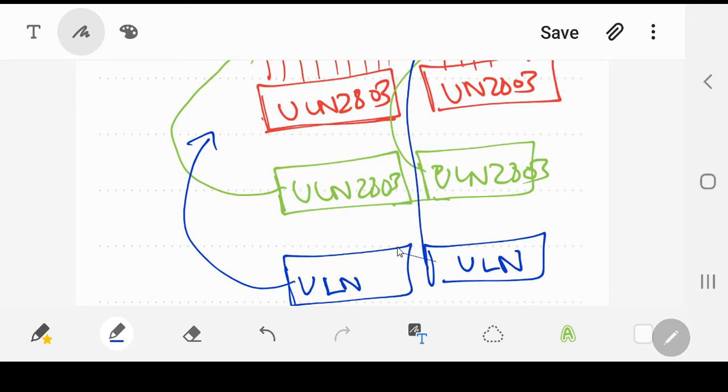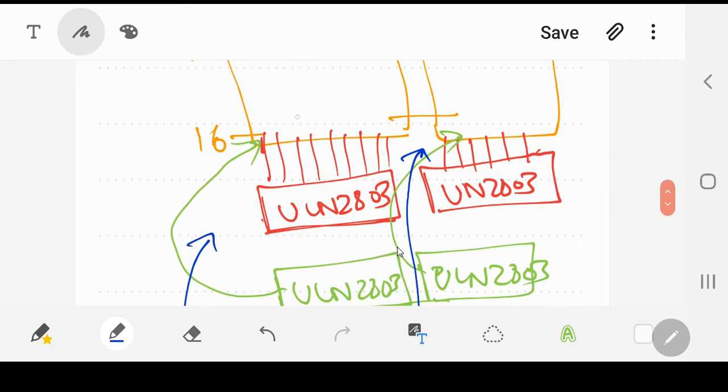This is, and certainly one thing very important, when they are going to be connected with the column, you will certainly have a resistor in between. That resistor is SMD in 1210 packaging, do not miss it. This is very important over there.